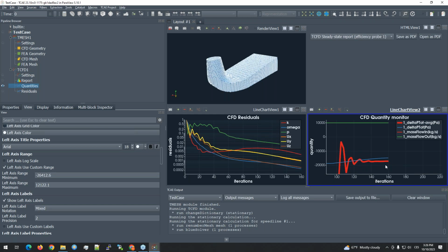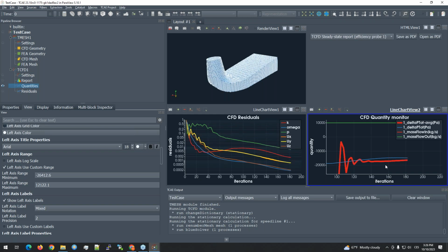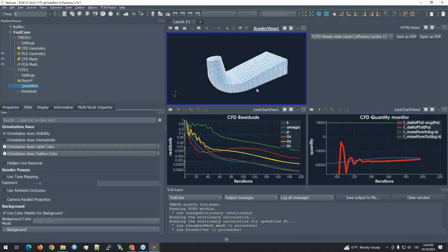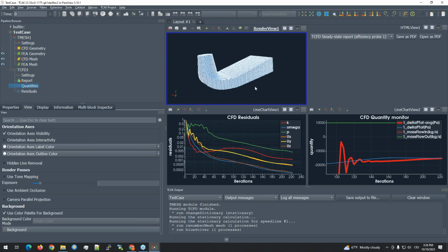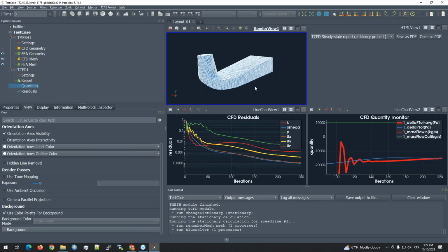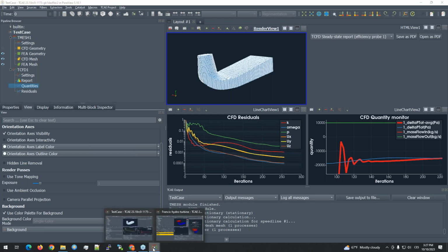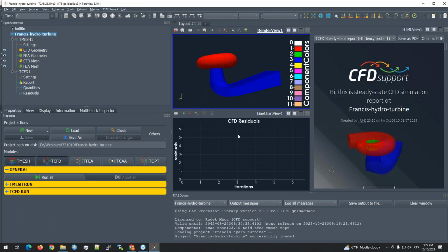And basically, roughly speaking, this is what you need for any application. Of course, the geometry is typically more complicated, so more STLs have to be set up and treated, and the mesh parameters have to be tested carefully and set, but the principle is the same to achieve the CFD simulation. So this was a very quick example.